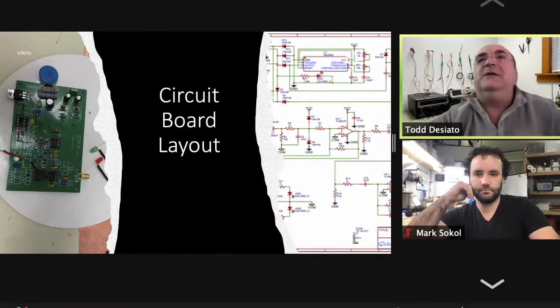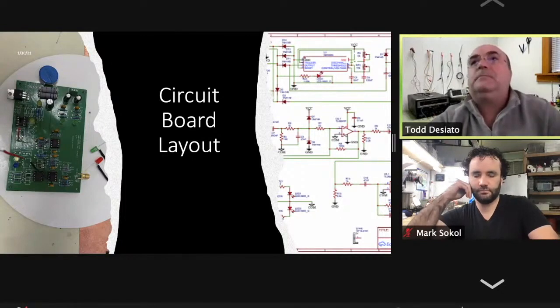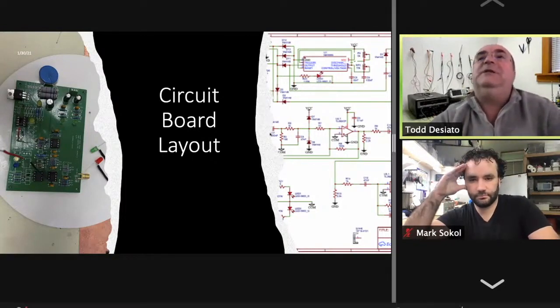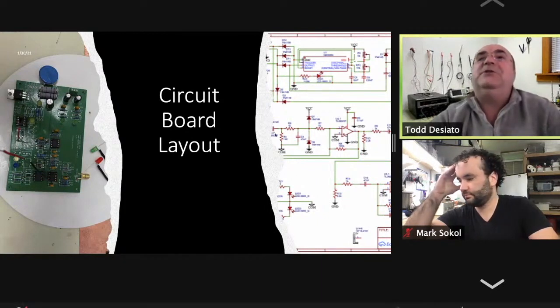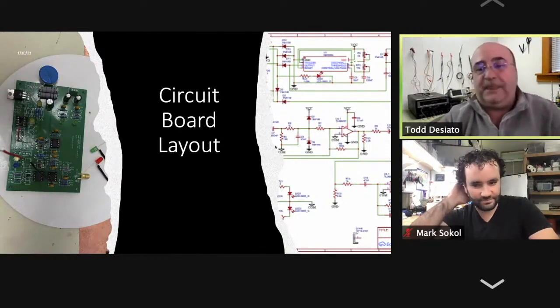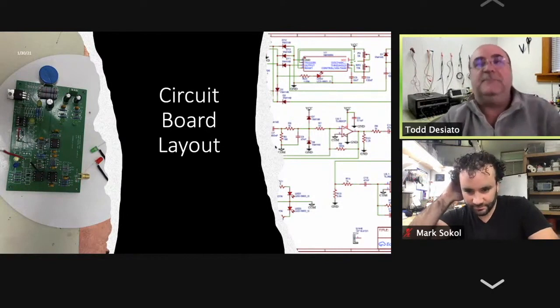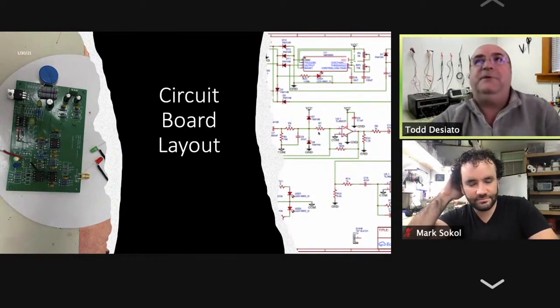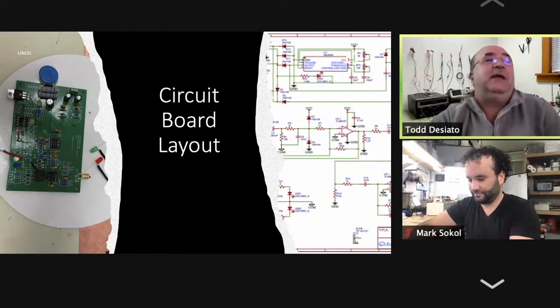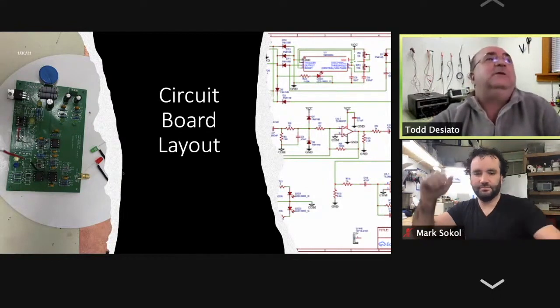The schematic is basically a timer with a fourth order bandpass filter, and that coil feeds into a capacitor, making it like an AM radio tuned circuit. So I tune it for the frequency I'm looking for from the resonance of the protons. And then I amplify that with a very sharp filter. And then that signal gets fed out this little SMA connector because my scope probes are way too noisy. And then that goes into my oscilloscope.